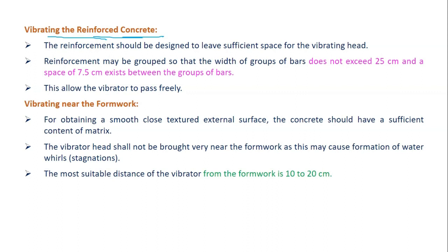So the reinforcement may be grouped so that the width of the group of bars does not exceed 25 centimeter and a space of 7.5 centimeter exists between the groups of bars.